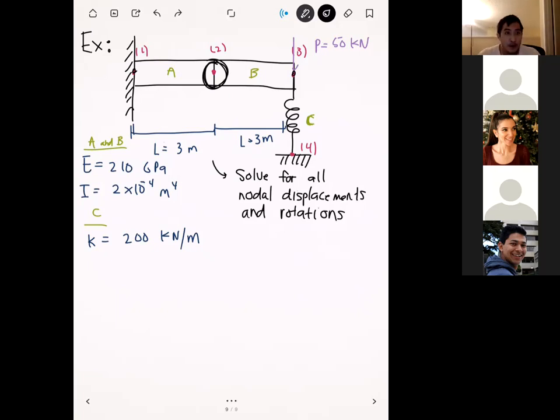And so the same concept applies there. The more elements that you have, the more packed together the nodes are going to be, and you end up with a result that's more accurate and a better spatial resolution, but it just ends up being more expensive because you have more things to solve. Whereas a coarse mesh is a lot easier to solve because you have fewer nodes, but you're not going to get as much accuracy or spatial resolution.